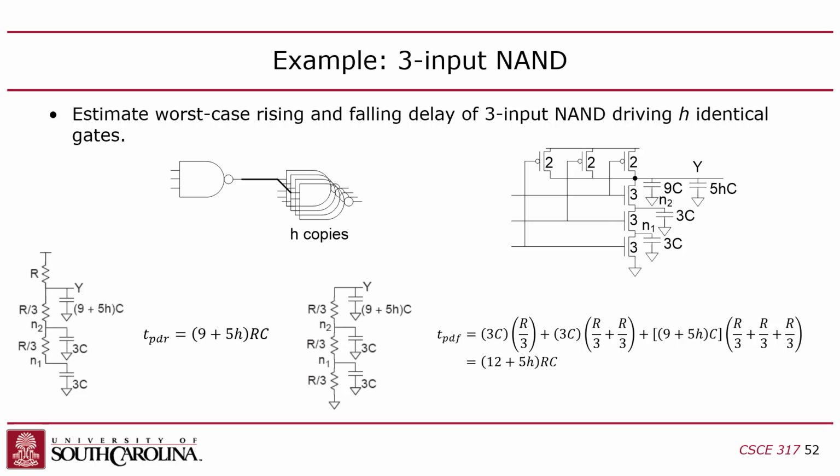Okay, so we can calculate 2 propagation delays here. Propagation delay rising and propagation delay falling. Now remember when I covered timing closure or timing analysis, we only talked about propagation delay and contamination delay. But here we can further break it down into the rising and falling propagation delay. Does that make sense? Because we can calculate these separately.